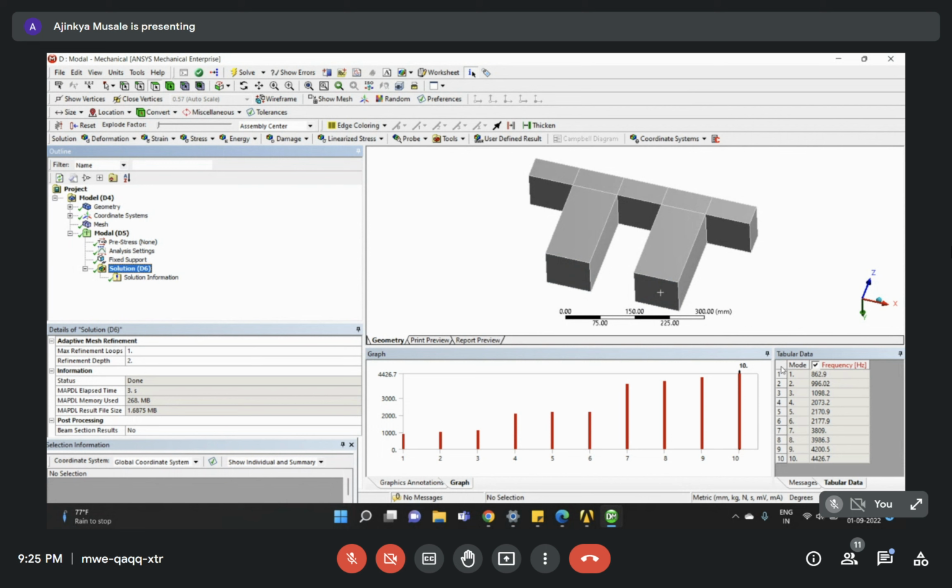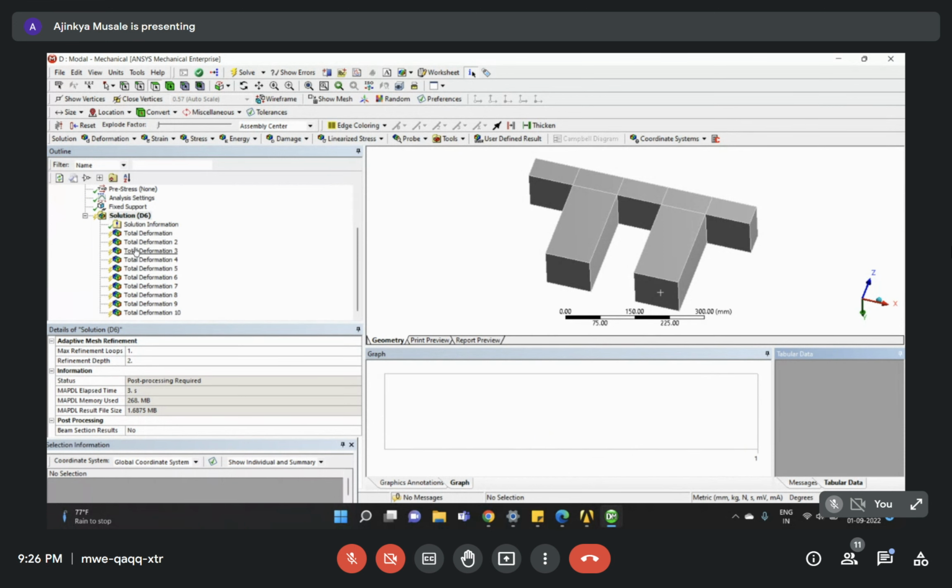So here, how can I select this then? Then means I need to press control, right? How can I select this? So we can select the top and then we can give it. Okay, selecting this empty cell. And then copy results selected option. Right click. Okay, just right click and say create mode shape. Copy results. Nice. Okay, so it will automatically create my mode shapes over here.